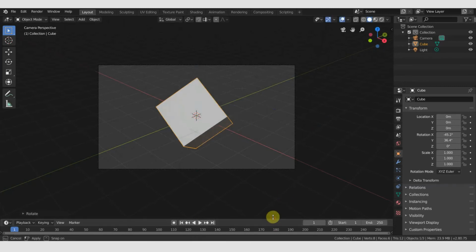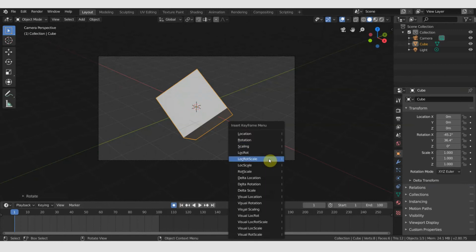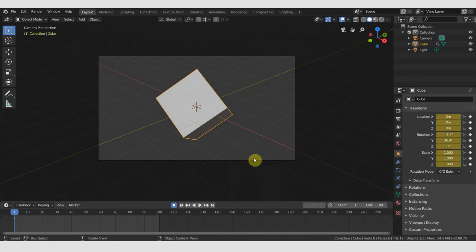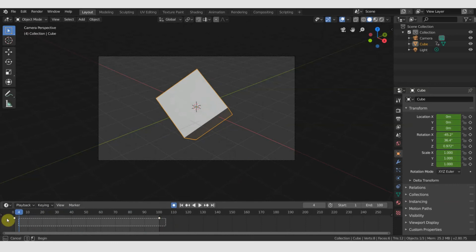So now we need to get our base rotation going. I only want 100 frames, I think that'll be fine. Let's turn on auto keyframing and then add a keyframe now. Then we want to go to 100 frames and add in another one, but we want 360 rotation there, and see what happens. Great. So it's doing a nice spin, but it's accelerating and then slowing down, which